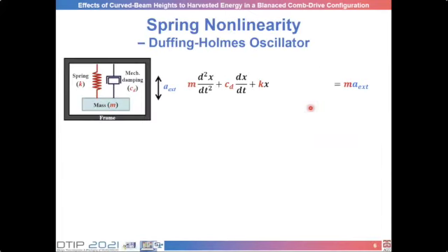Yet another approach utilizes spring nonlinearity, which can be described as Duffing-Holmes oscillator. Here we have an illustration of a typical mass spring damping system. And this system can be described by this motion equation. When there is a spring nonlinearity, these two terms appear.